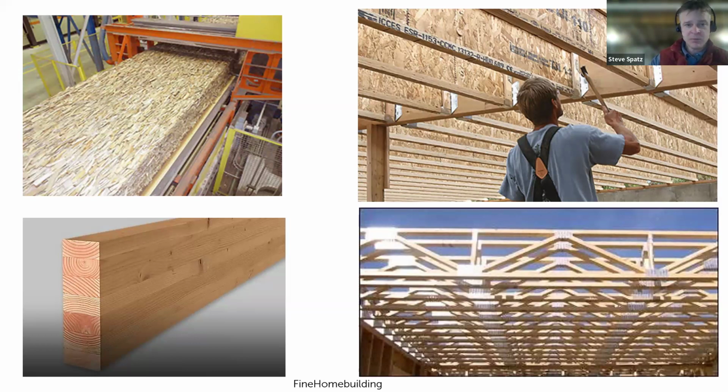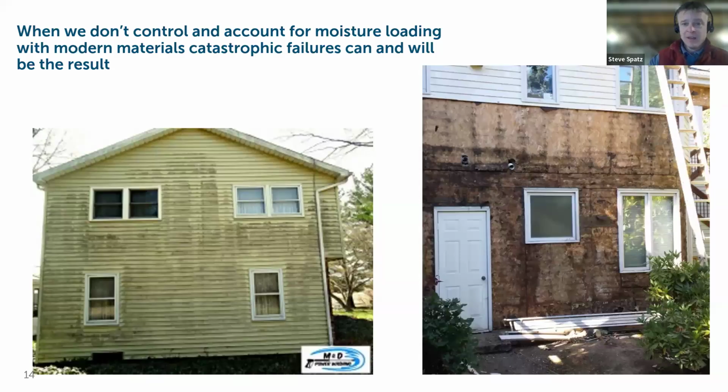It's essentially, like I said, bark mulch put into a functional form. So there are some pretty precipitous and significant consequences that can come out of that dynamic change in the use of the material. And if we're not accounting for that in the layers involved in an assembly, and where we could have potential points of damage immediately and in the long term, then these things can go hidden for years and decades before the evidence of that inability to manage moisture and the changes in the material will show up.